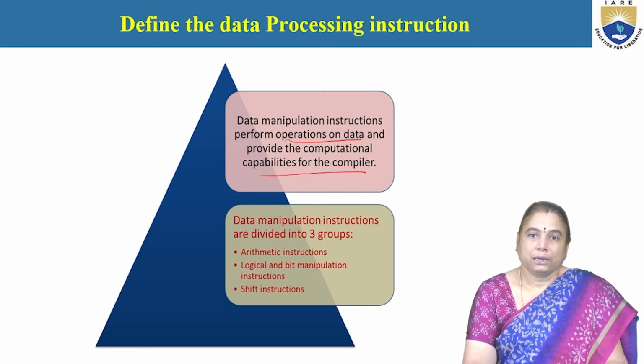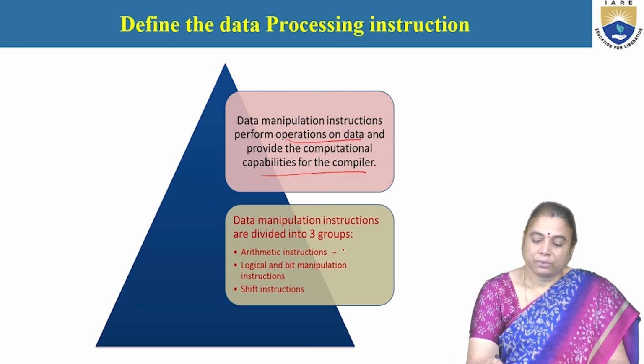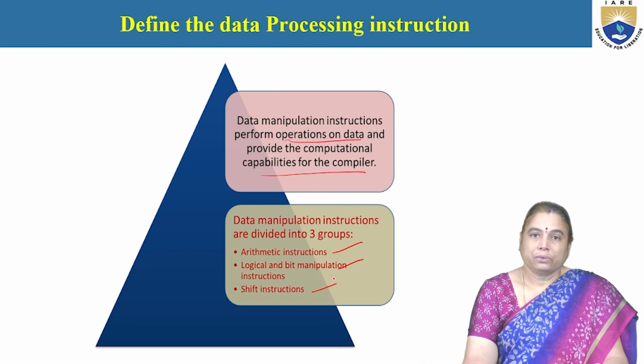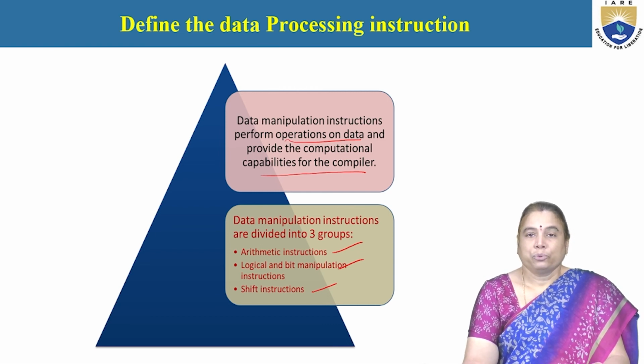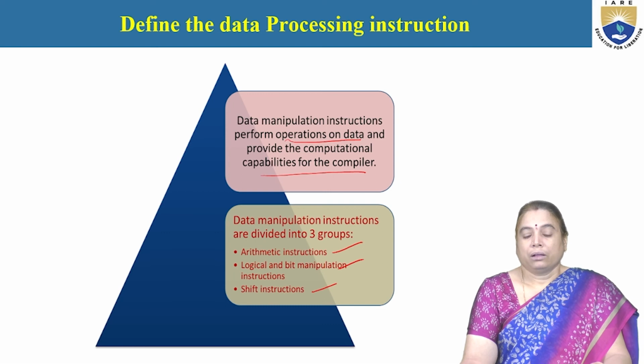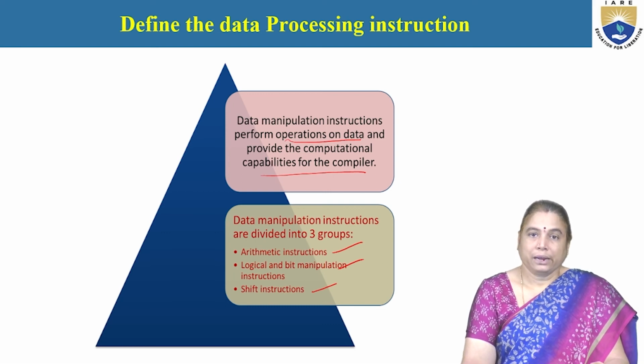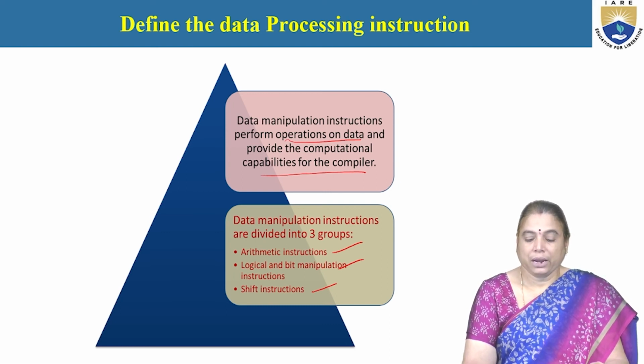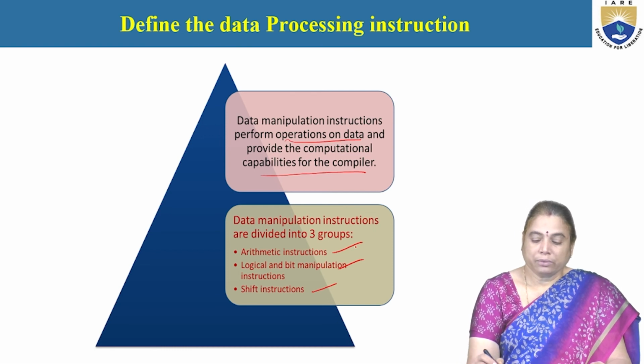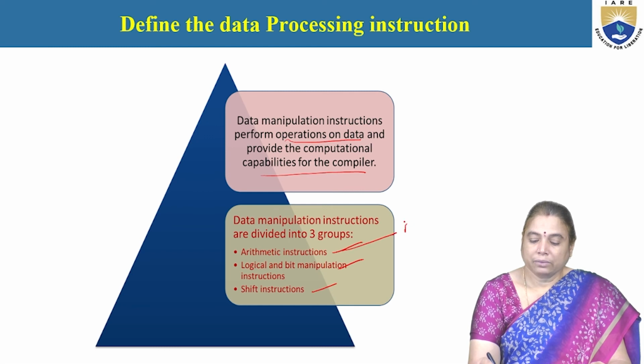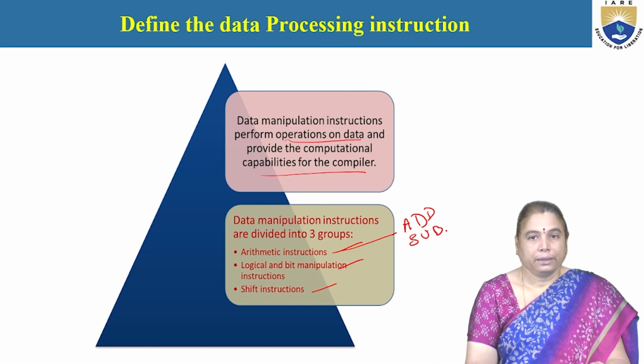There are 3 categories of data manipulation instructions: arithmetic instruction, logical and bit manipulation instruction, and shift instruction. Arithmetic instructions are generally used to perform arithmetic operations like addition, subtraction, multiplication and division. To support this, the mnemonics available in arithmetic instructions are ADD, SUB, MUL, and so on.